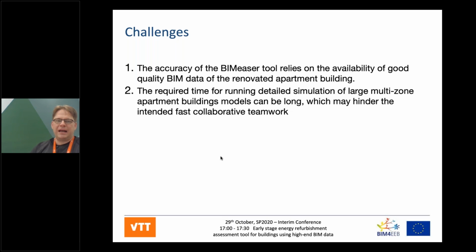Then it's always balancing between simulation time and details of the system. If there are large buildings and they have many simulation zones, so there are different parts of the building that are separated in the simulation so that you can get energy consumption and temperatures and conditions for every room, for example, then it easily gets quite heavy and the simulation might take too much time to be run in that coffee break.